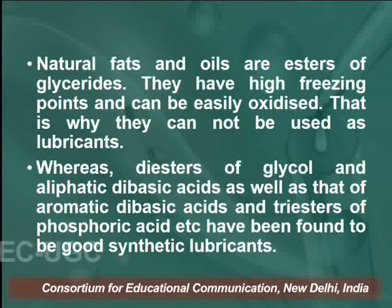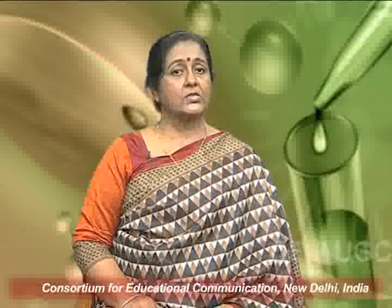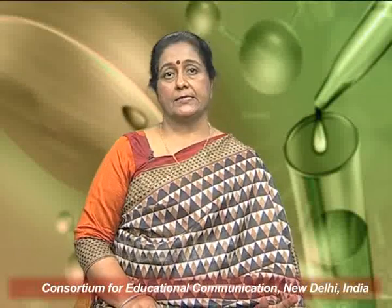Natural fats and oils are esters of glycerides. They have higher freezing points and they can be easily oxidized. That is why they cannot be used as lubricants, whereas diesters of glycol and aliphatic dibasic acids, as well as those of aromatic dibasic acids and triesters of phosphoric acids, etc., have been found to be good synthetic lubricants.